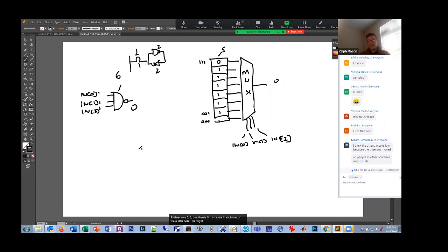And this mux, if I want an 8-to-1 mux, what's an 8-to-1 mux? It's 7 2-to-1 muxes, right? We learned that before, right? If you have 8 inputs, it's n minus 1. So that 8-to-1 is like a 4-to-1 and a 4-to-1 and a 2-to-1. And each of those 4-to-1s is three 2-to-1s. So this one's got 3 and this one's got 3 and that's one more. So there's 7 of them, right?